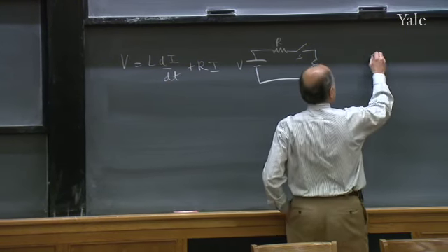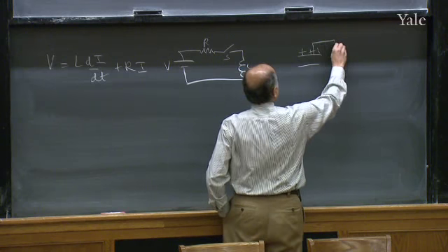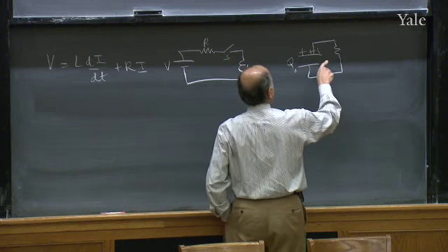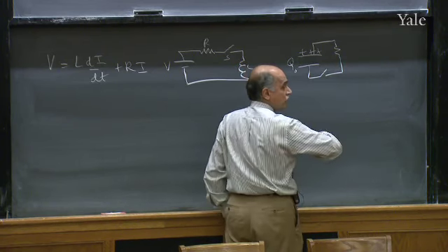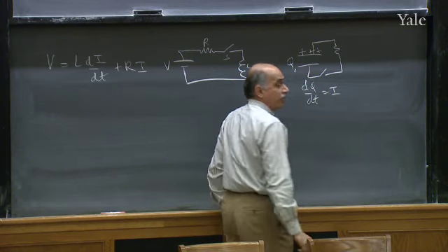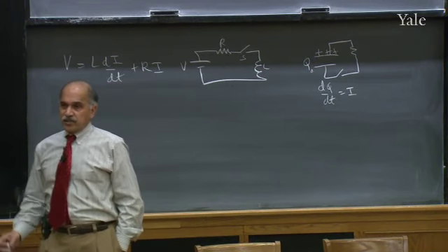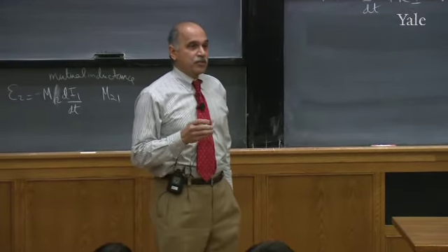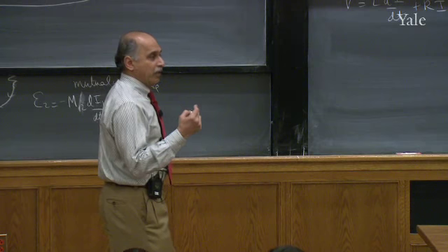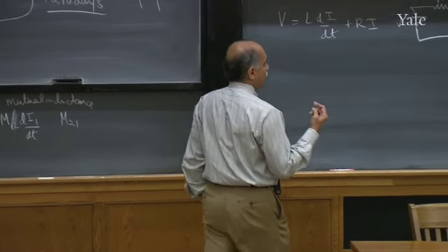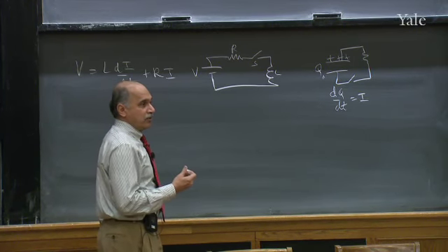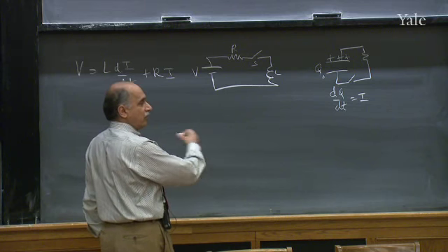Likewise, if you have a capacitor with some charge on it, and you close the circuit, the charge on the capacitor, initially Q naught, will remain Q naught 1 femtosecond after you close it, because the rate of change of the charge is the current. The current is finite in any real problem. So capacitors cannot abruptly change the charge they have, and inductors cannot abruptly change the current they carry. And if you want, they are connected to energy. The energy in the capacitor is Q squared over 2C. Therefore, if Q changes abruptly, the energy changes by a finite amount in infinitesimal time. Nobody can deliver that energy or take out energy at that rate.